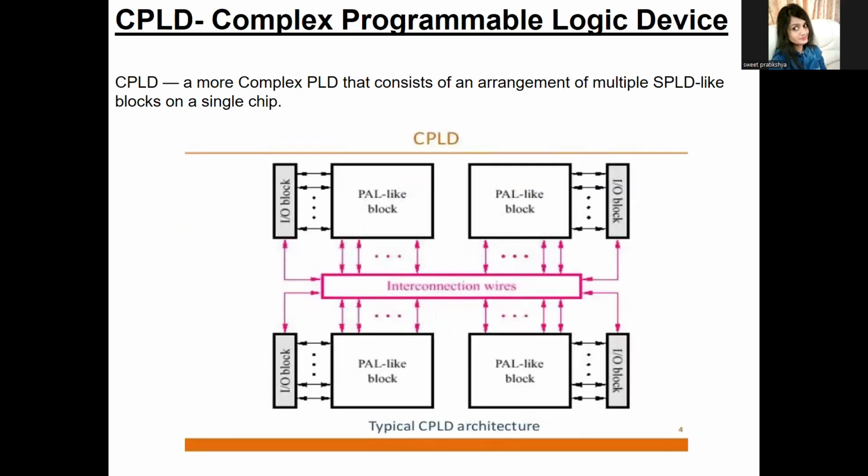So what are the features of CPLD? Let's break down the CPLD architecture. Logic cells are the basic building blocks with AND or XOR gates and a flip-flop. As we studied, they have multiple macro cells in them, and macro cells contain a group of logic with added features. The input output block connects the CPLD with the outside world, that means it connects with external devices.